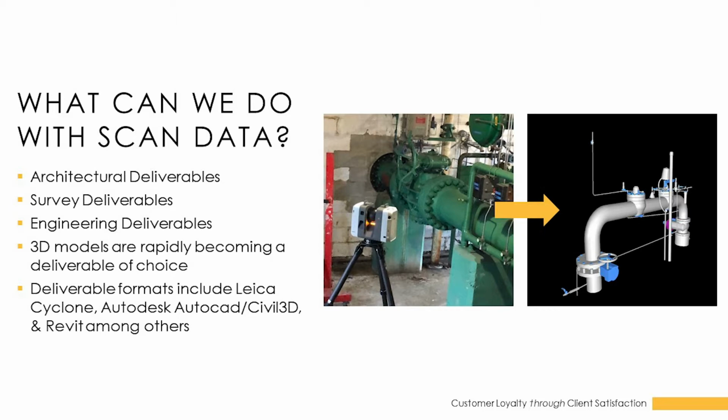Okay, so as CJ mentioned at the start of the presentation, laser scanning is based on line of sight. You would be forgiven for thinking sometimes, if you look at the quote unquote point cloud, that the scanner can see through walls. That's understandable. But the way the scanner works is you set the scanner up in front of the subject matter to gather the information, and then you move the scanner to different locations to surround it, just as if you were taking photographs.